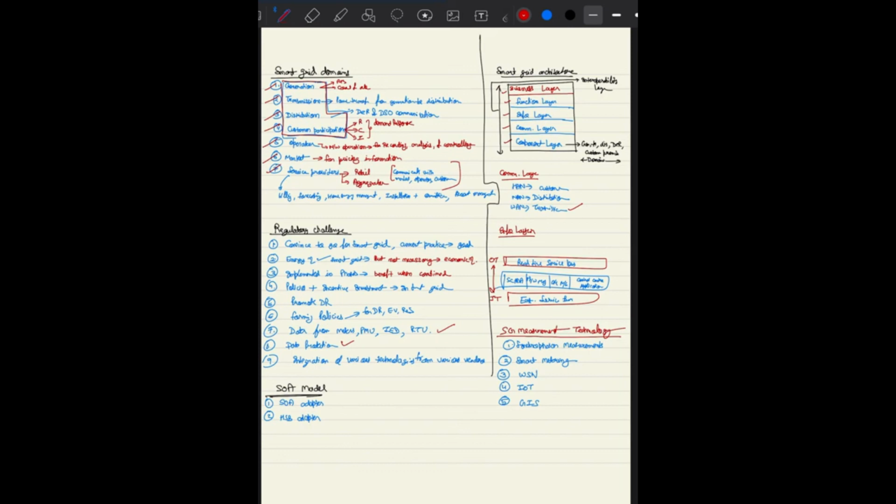Then comes our smart grid information layer, which I already discussed. It provides IT and OT convergence, in which in between we have SCADA, network management, outage management, and historian network planning. On the top there are some legacy applications and intelligent field devices. Here we have CIS, ERP, EAM, advanced metering infrastructure, and market.